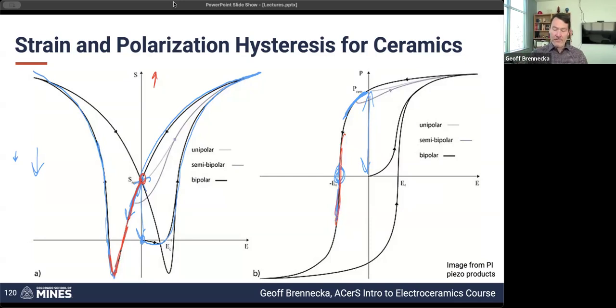Hopefully that makes sense. If you're drawing these hysteresis loops, or if you're measuring something, that's why you end up with this butterfly shape. So you can probably imagine that if you're operating this in an application, you probably don't want to go through that kind of a transition over and over again, because that's going to be really hard to control what your sample is actually doing. So most of the time, for most applications, people will be operating in this region. So you stay away from the coercive field because you don't necessarily want to switch a bunch of stuff during the operation of your sample.